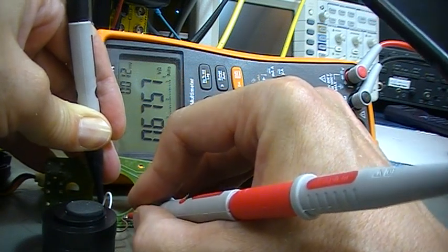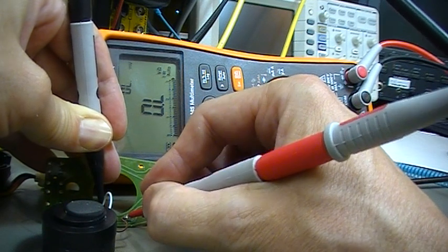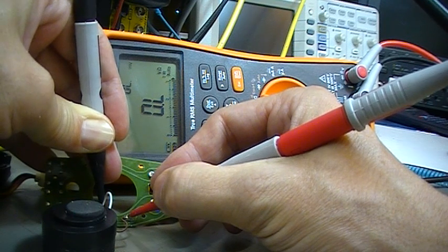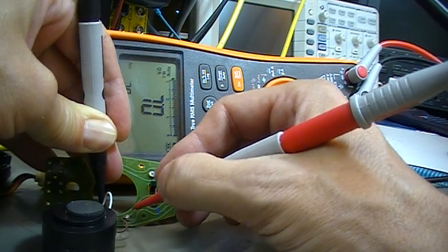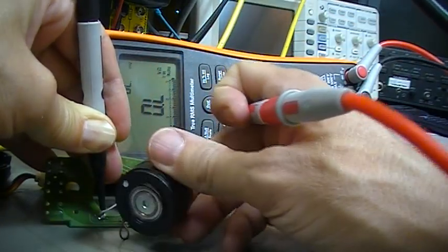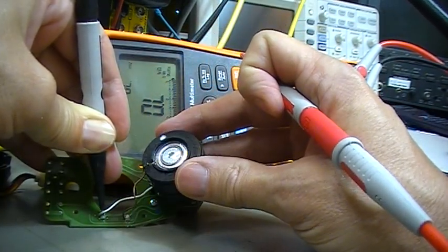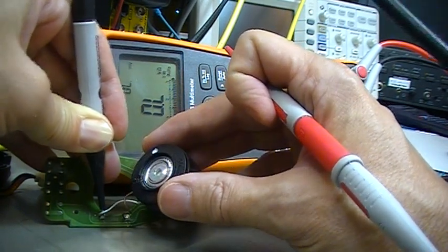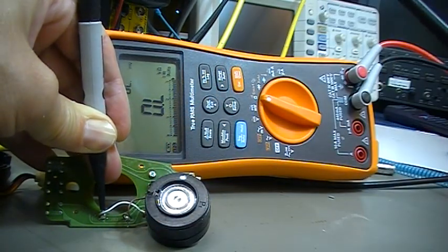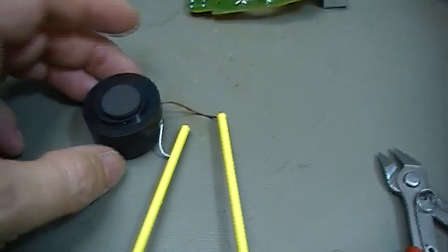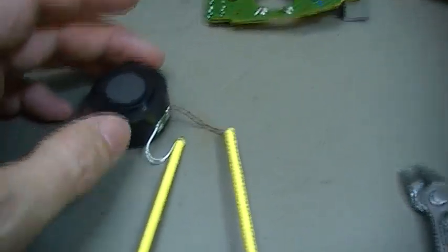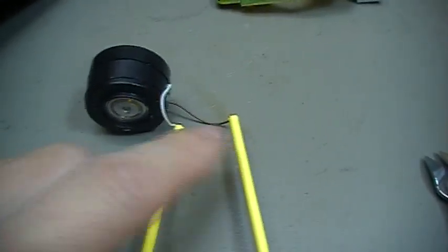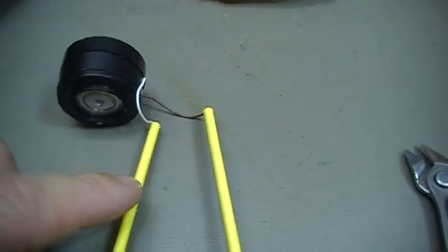And now back to the capacitor in between, you see now there is no resistor anymore, and therefore I would say this capsule is faulty. So that is obviously the reason for the problem. Here once again I have disconnected the capsule from the PCB, and it is now directly connected to the ohm meter.